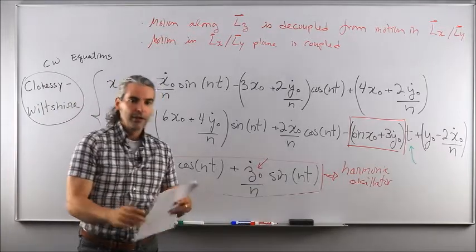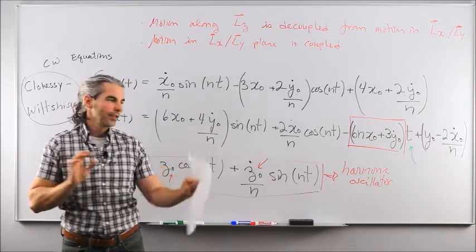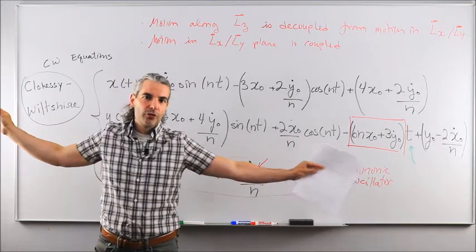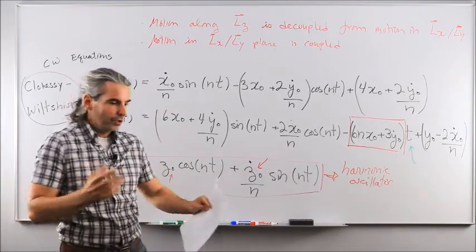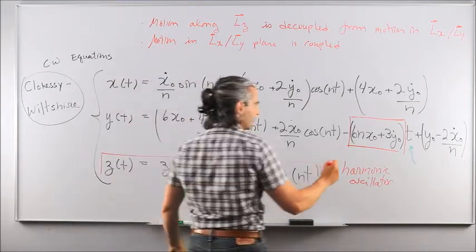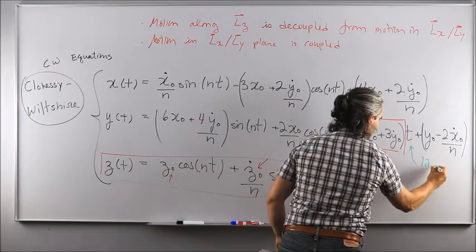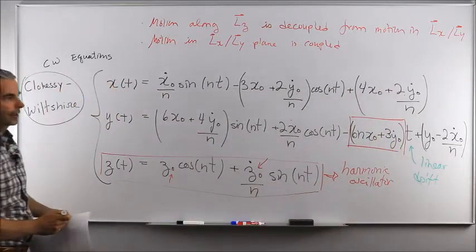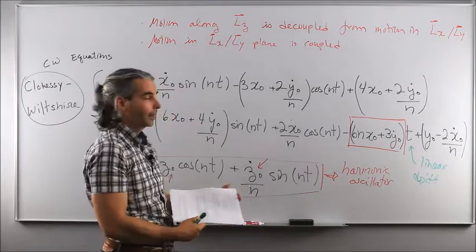Or in other words, the two spacecraft, which would start very close to each other in LVLH, would start to drift along one axis. And specifically about the Ly direction, you would see a linear drift that would keep increasing with time. So the formation would drift apart, essentially. Unless you apply corrective maneuvers, passively the spacecraft would just drift apart and you would lose the formation. So that's not a good thing. What we want to do typically is to figure a way to cancel this bad term here, which is known as a linear drift with time along this particular axis. So this is a bad effect, and we want to cancel this out. Let's just keep that in mind for what's coming up in the next subsection.